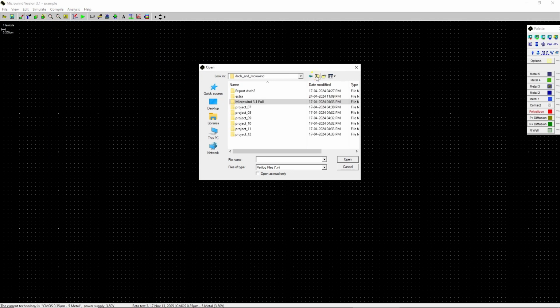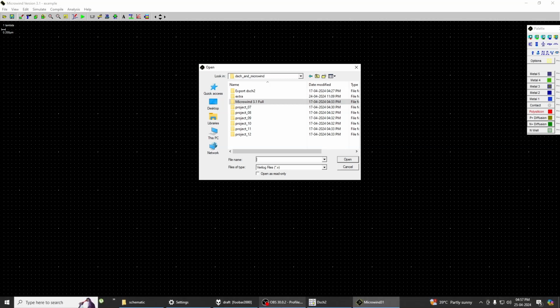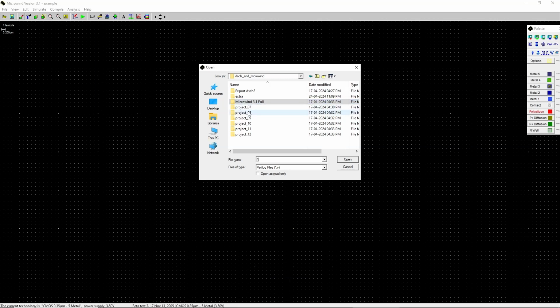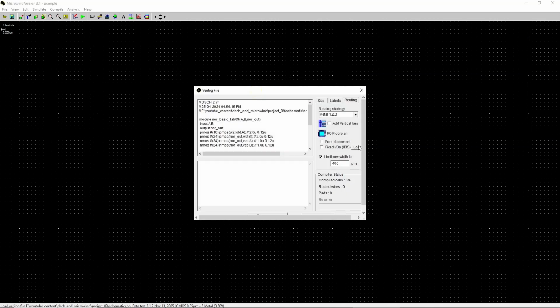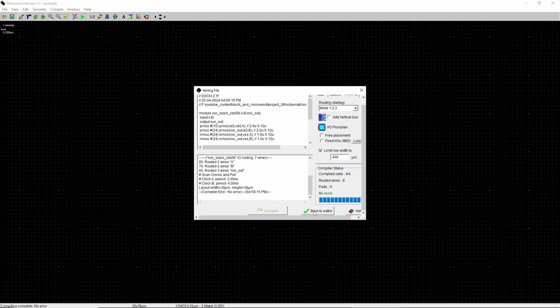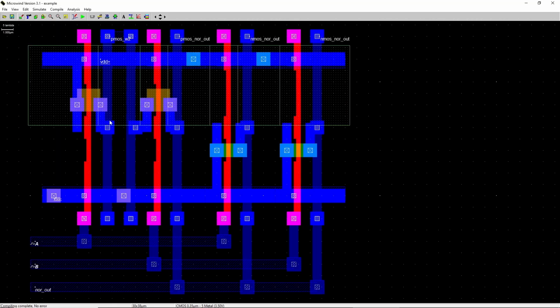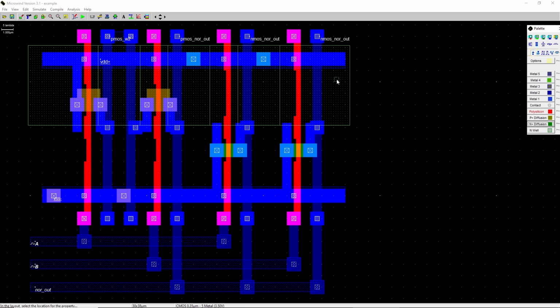Once again, we shall compile our Verilog file created from Schematic. Now, you'll see just two NMOS and two PMOS devices. All the input and output nodes along with ground or VSS and VDD are already connected in the layout. Click on Show Palette icon to see layout components. Connect a VDD node to NWEL region also. Now you're ready for another simulation.